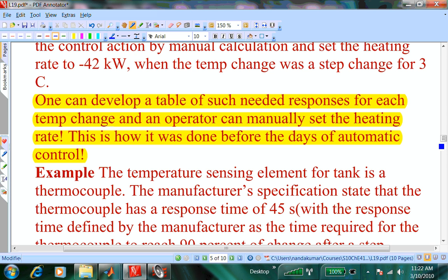Another way, when I talked about this control station, you just make a change. The process is so complicated, you cannot build models. So you make a change in the inlet and observe the outlet change, and then fit a first-order process with a time delay. So you get these two constants experimentally. Then use that in your feedback control. It would work. But feed-forward requires very precise knowledge about the process, that you can know a priori and predict and then take a compensating action. That is an algorithm that is used, but it requires a very good knowledge of the process itself.